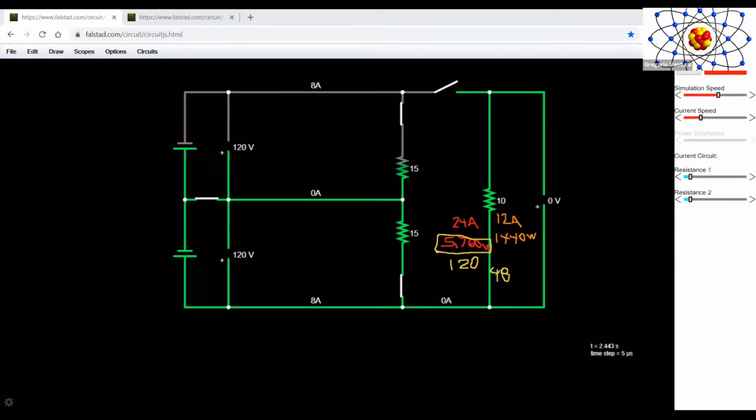And having 48 amps instead of 24 to have the same amount of power would translate into having a way thicker wire, a bigger gauge wire. And also the overcurrent devices would need to be way bigger. We would need overcurrent devices rated in this case at 60 amps, rather than an overcurrent device rated at 30 amps. Can you see the difference between these two different voltages?